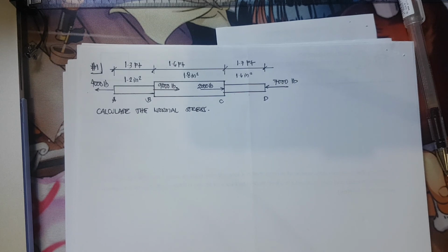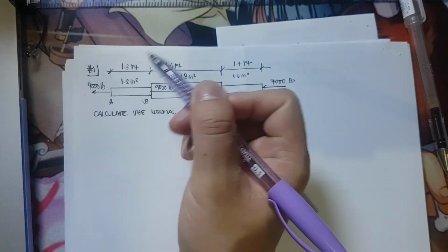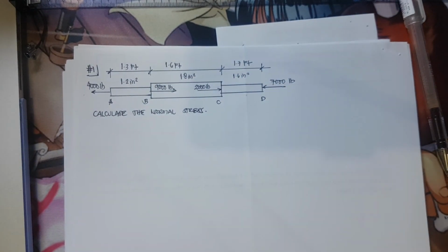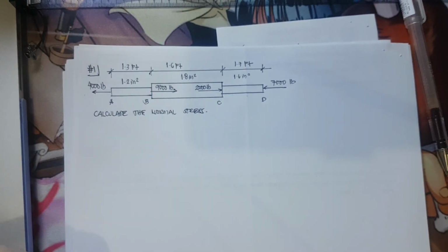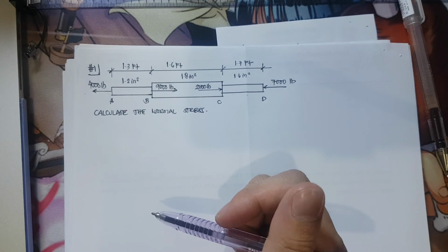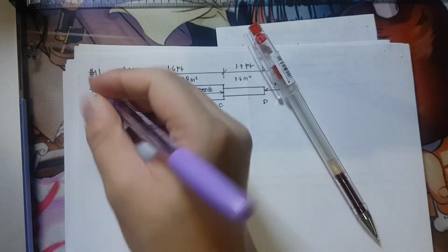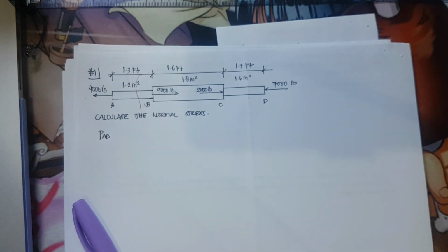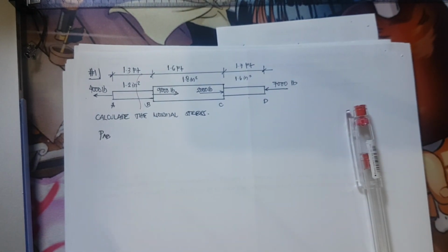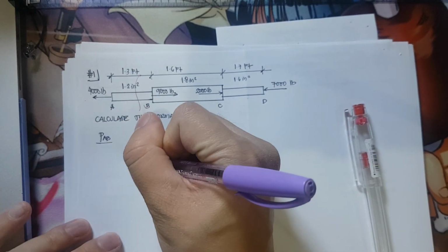Okay, so from our discussion, we were able to discuss that if the force or the actual force is going away from the material, therefore it is tension. We will be using that shortly. Okay, so let's try to solve. If I am to determine the force PAB, I am going to cut my section at this portion. So with that, I'll be introducing the free body diagram of PAB.